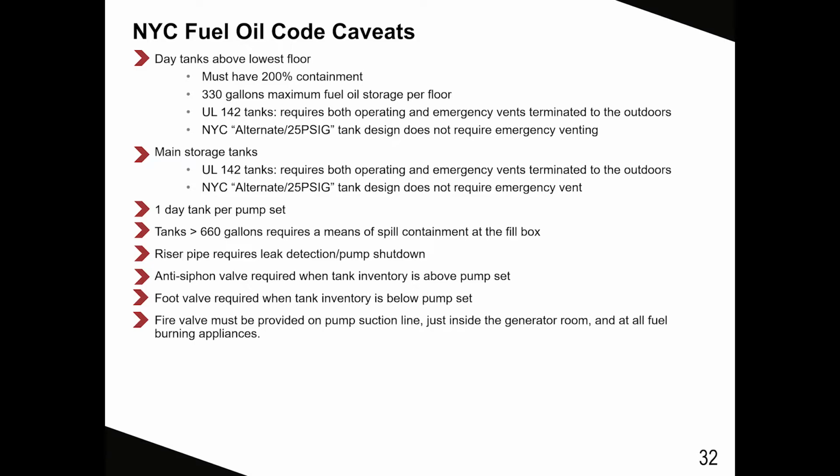1 day tank per pump set. Tanks in the basement over 660 gallons requires a means of spill containment at the fill box. All basement tanks are in a 2-hour fire rated room minimum. Riser pipe requires leak detection with pump shutdown logic. Anti-siphon valves are used on tanks when the inventory is above the pump inlet. A foot valve is required when the tank inventory is below the pump inlet.